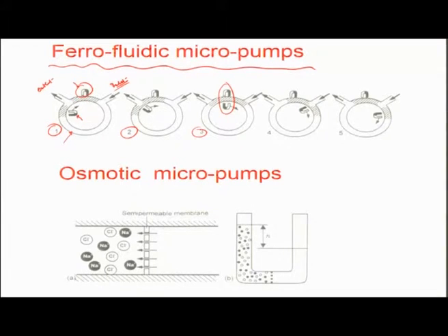And this again has a sort of a ferrofluidic pump, with ferrofluidic material shown by the hatched lines in both these cases. As the magnets are separate, that is the core magnet is separate and the flank magnet is separate, it attracts its own ferrofluidic material, and as they come face to face, the material joins together as one particular plug.